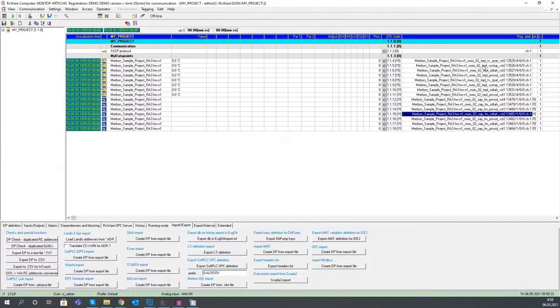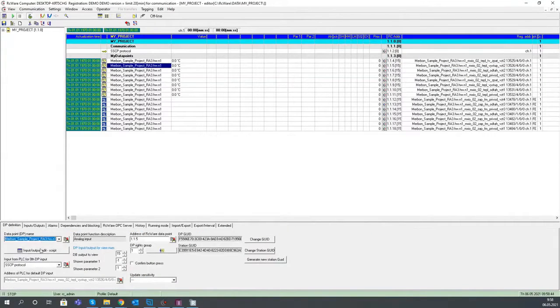So here, for example, this is the supply temperature of air handling unit 2, and this is what I can do here. Like this. So that's an easy way for me how to change all these data points and assign them some reasonable or easy to read names.